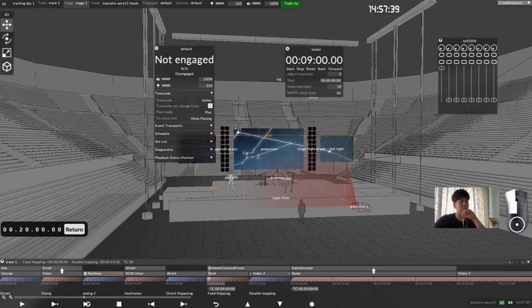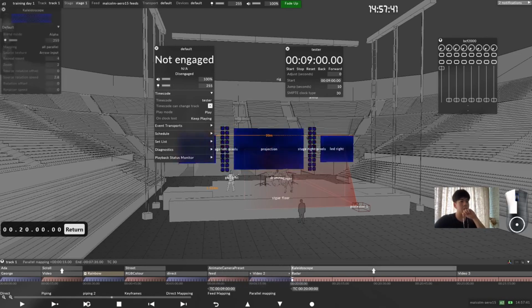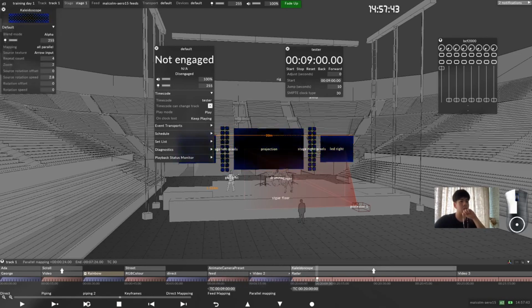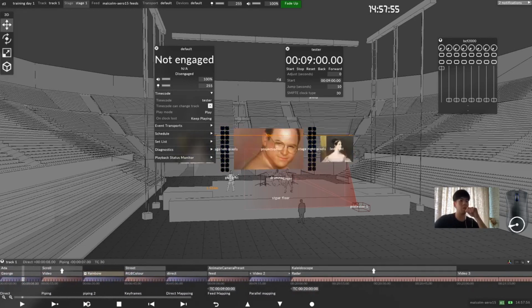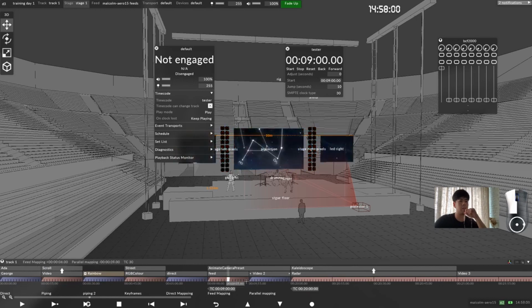You can see the timeline starts from 9 minutes and ends here, then it waits for another trigger. By adding timecode, it doesn't mean all your layers will be shifted to that exact timing. It will override the existing timing and put your layers on it.